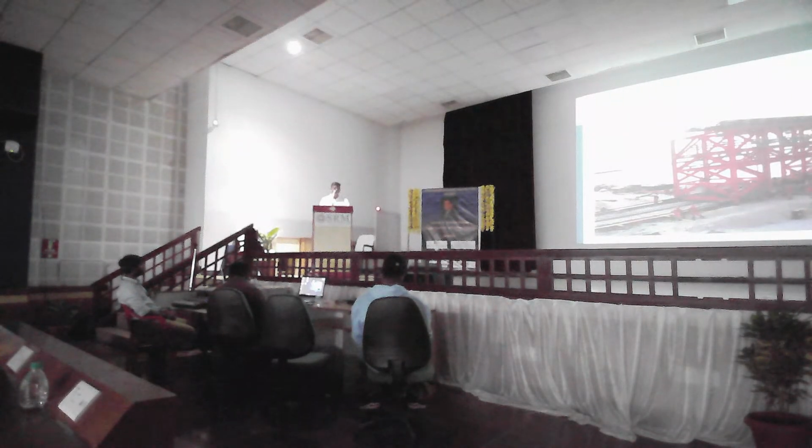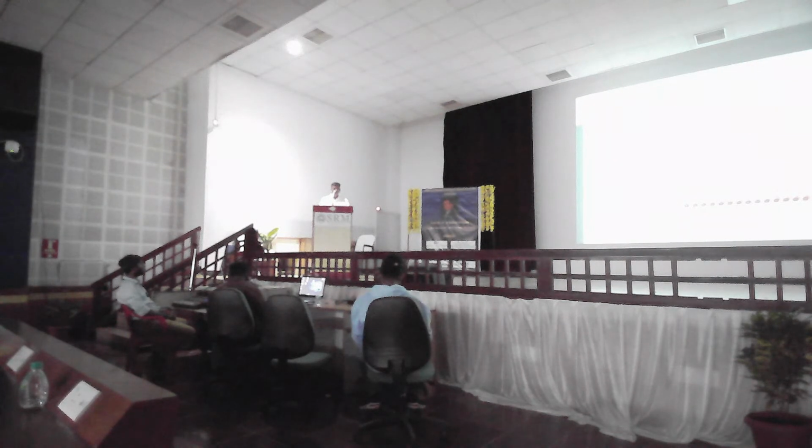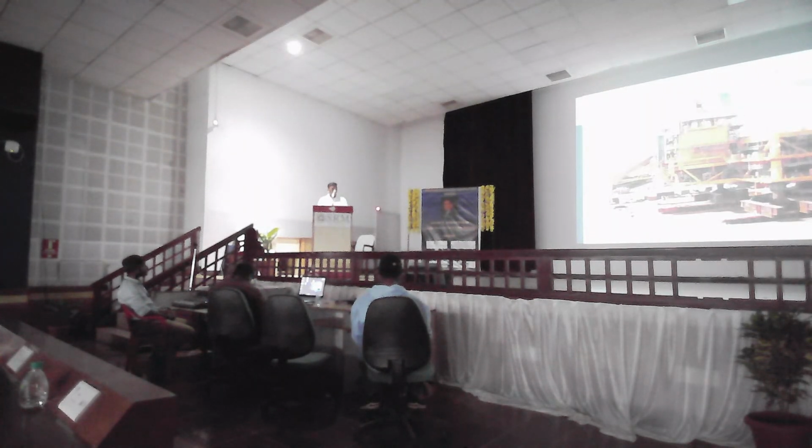This is a typical picture for skidder load-out. When the weight is heavy, as with a pipe rack, people are skidding it there. You can see some rails are placed below. This is skidder load-out. And this is a typical trailer load-out scheme. We are placing two trailers here, and the modules will be placed on top. This is a typical trailer load-out.